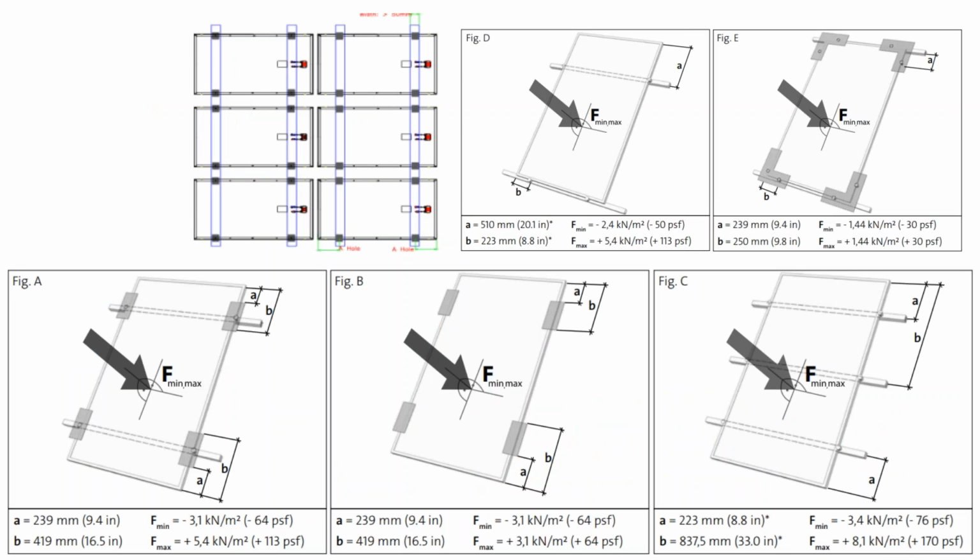You read the module installation spec sheets, and they'll give you force load ratings for the panels, which can be impacted by your racking structure. So you may be able to increase the weight of the array using the same panel, but adding an additional support rail underneath it. Or certain racking types may not have this support rail.